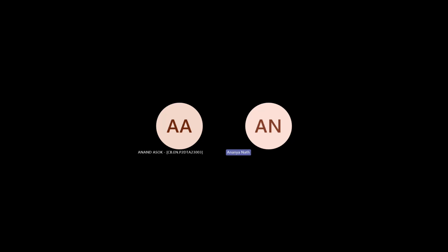In the case of tool path, there are two steps. One is the area filling. The second one is the contour. Area filling means the whole layer. If the layer looks like this, where there is a hole inside, then this is the area that needs to be filled with the material. In the case of LPBF, only the laser will scan this whole area very fast.